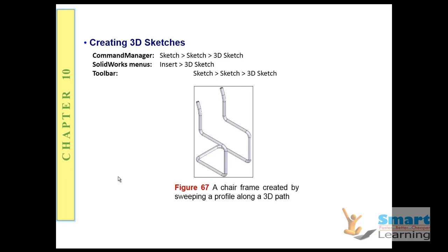In this session, I will be discussing 3D sketches, how you can switch from sketch mode to 3D sketch, how to create the 3D frames, and how you can use the different controls. So let us create this chair frame and do the sweep operation over the 3D path.